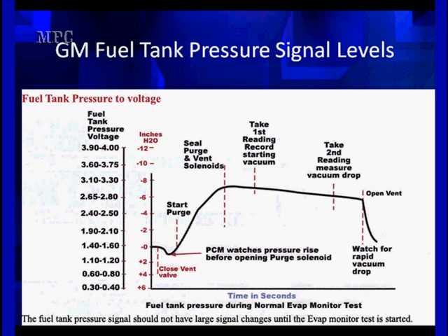Here's the overall thing. Here's start to finish. We started off at 0. We closed the vent. We closed the purge. When it's warm weather, we might get a little pressure rise. You might see it dip down a little bit. If the dip is too big, it'll abort the test, but this is just checking to make sure everything's normal. Then it's going to start purge duty cycling, pull a weak vacuum, stop, hold it. Purge solenoid and the vent solenoids are both closed.